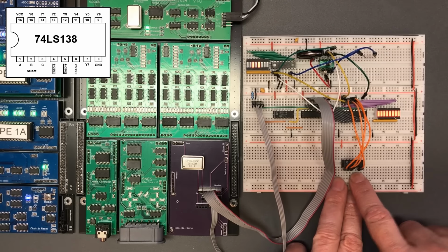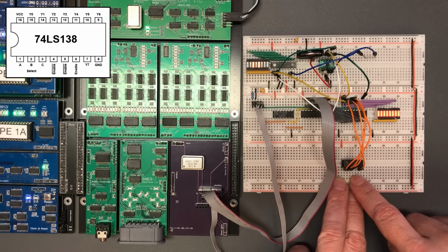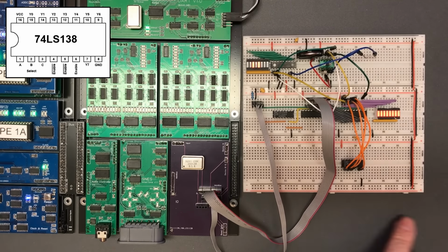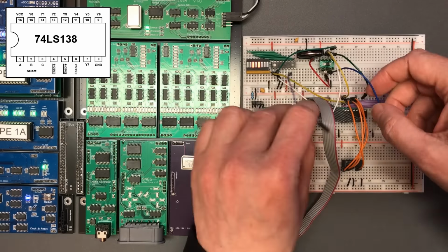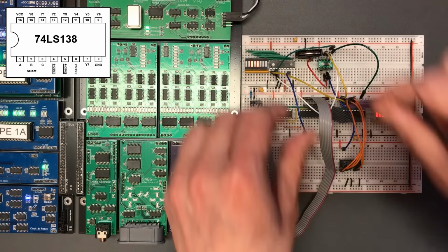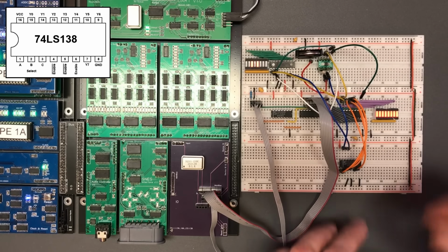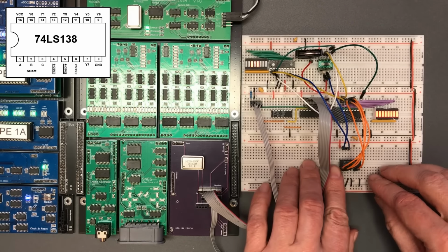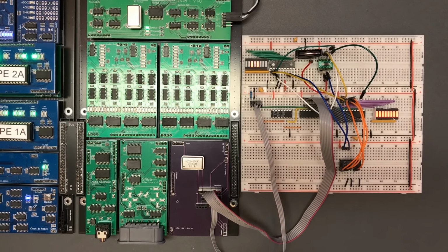These 2 are active low enables, but we're not using them right now, so I'm just going to pull them down. So the RTC becomes device 8 and the MCP is device 9. Very simple circuitry addition there, but let's go and see if we can modify our code to support that.